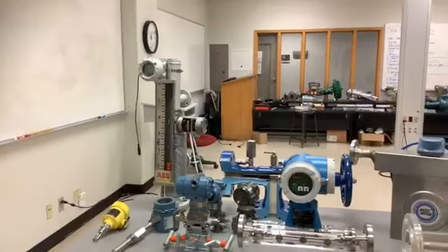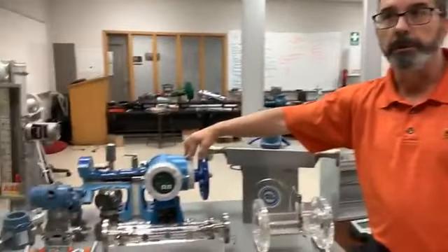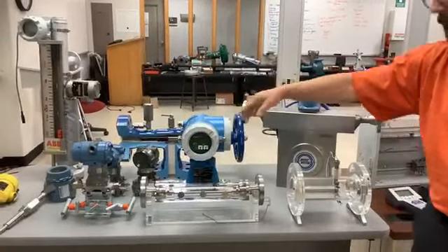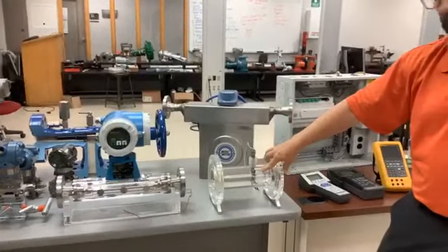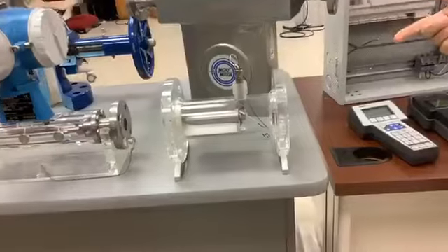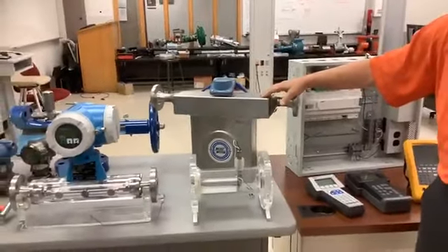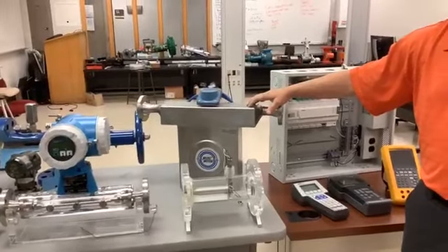Now you're not just going to learn what these are, you're going to get to learn about the physics of them too. So for example, this flow meter right here uses the principle of ultrasonic physics in order to measure flow. This one uses a turbine that you can see if you get down in there close, and it produces pulses that we count to measure flow that way. And this one uses the physics of the Coriolis effect. That's Coriolis. I'll let you guys look that up on your own later, okay? But it's pretty cool.